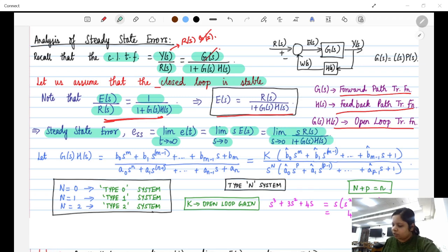It is very simple. So G(s) can, let's say, be some polynomial as numerator and some polynomial as denominator. Now what we want is to get rid of any s term. If we are able to take out any s term as common and separate it, that would identify the type of system. So you can see here for this numerator, you cannot take out any s, or if you were able to take out, then also you would have some s outside.